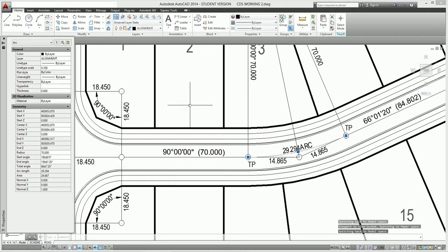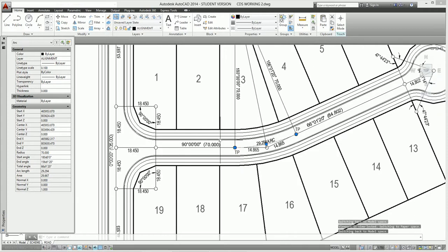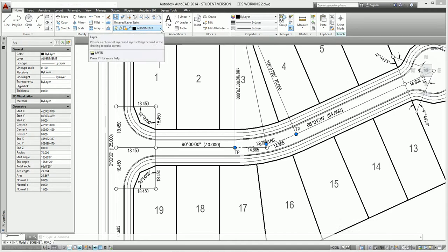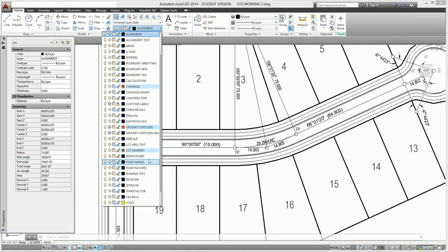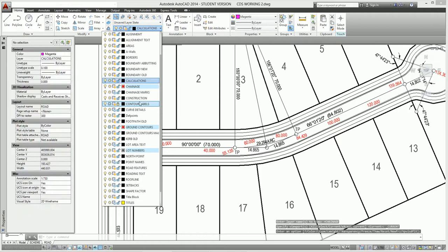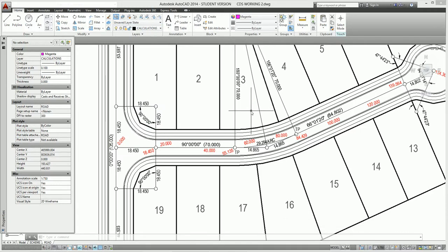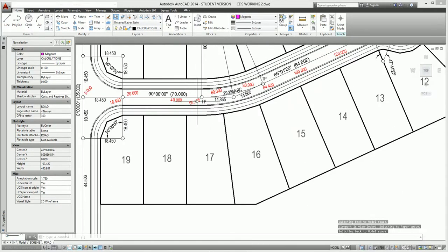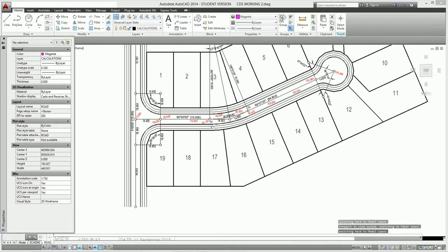Now, what that enables us to do is calculate some critical changes at this point in time. I have done some of this previously, so I'll turn on a chainage layer here. I've got a few extra marks in there, so that gives us the chainage marks, which I've got all in there ready in their approximate places. We're going to try and work out a chainage every 20 metres.